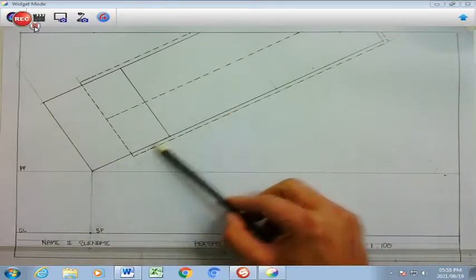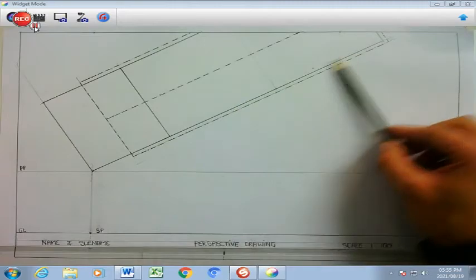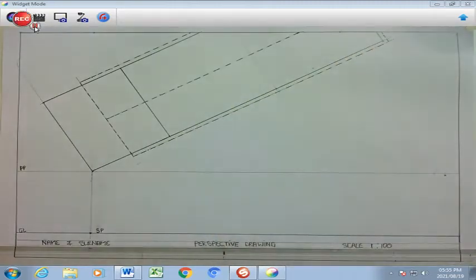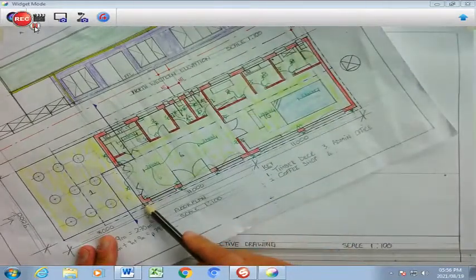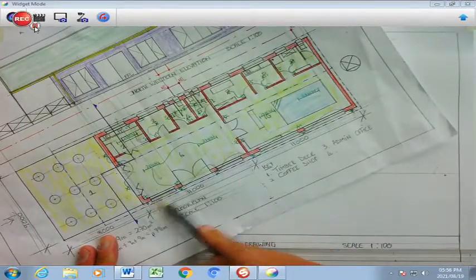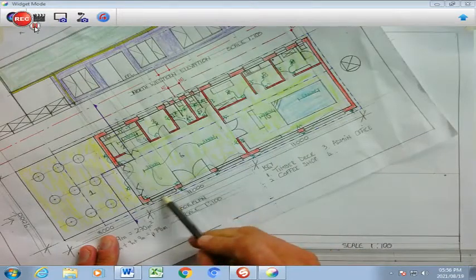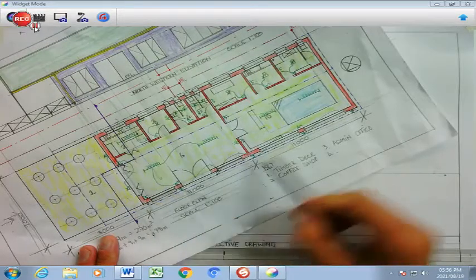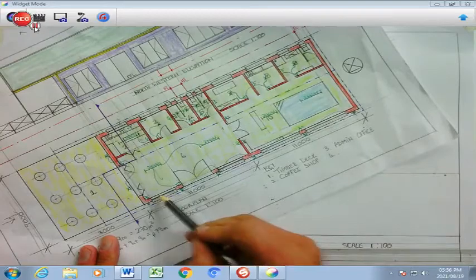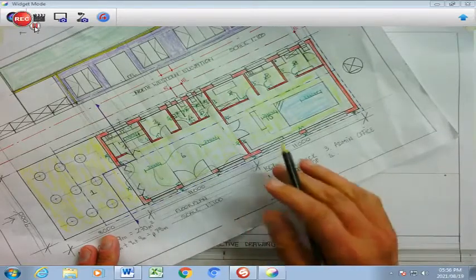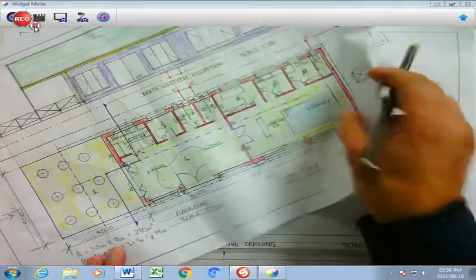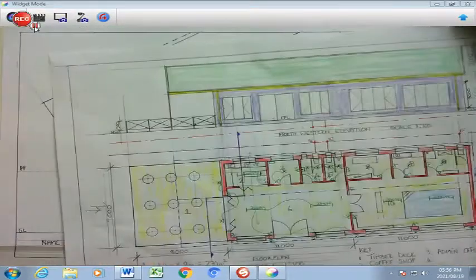And just keep in mind there are going to be some windows and doors here which I'm going to put in. And what I'm going to do is measure the distance here and just apply all these distances away here by just marking it. I'm not actually going to put in the windows, I'm just going to mark where it's going to be and label it window, door, so that I know when I'm going to project it down what I'm dealing with.